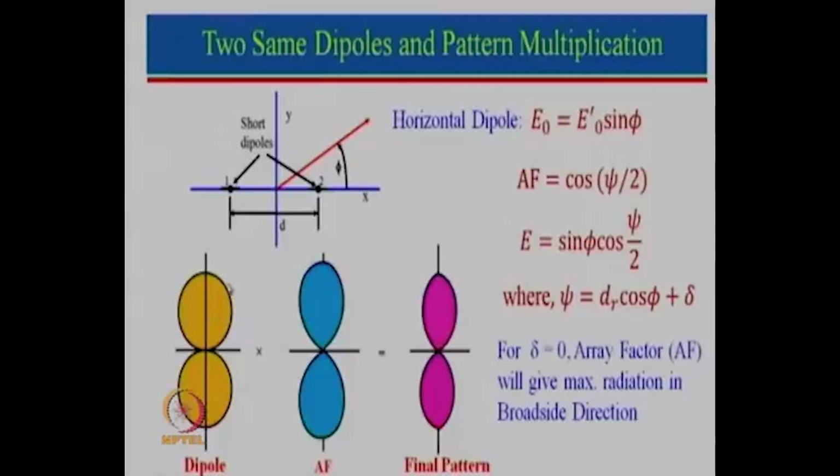So in the form of equation, we can write the equation for the dipole. Now this is sin phi. It is important how phi is mentioned and measured. In this case, phi is measured from the x axis. So in this direction phi is equal to 0, so sin 0 will be equal to 0, and that gives the minimum radiation, and at phi equal to 90 degree, sin 90 will be 1, and that gives the maximum radiation here.